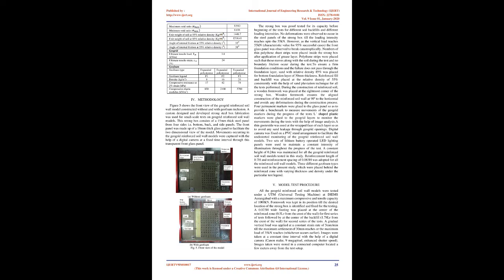At the same time, when the footing is placed over the backfill, a similar mechanism of geofoam compression would occur. The compression occurring in the geofoam mobilizes the backfill shear strength, resulting in lower earth pressure than the theoretical predictions for the without geofoam case. This compression in geofoam also provides a wider distribution of the applied load. The amount of shift in the load distribution lines depends on the compressibility of the geofoam. Due to this shift, the vertical stress at any point below the surface will be lower than in the without geofoam case, which ultimately would produce lower lateral earth pressure.